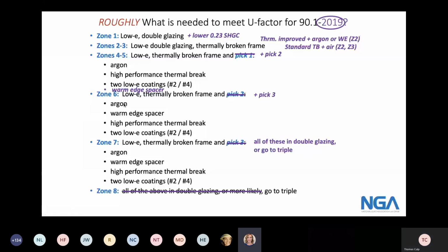Okay. Another related question. Why is there such a sharp reduction in U factor for commercial entrance doors from 0.77 to 0.63 in ASHRAE 90.1? Yeah, that's a good point. So we went through and just kind of surveyed some of the manufacturers, we meaning the ASHRAE envelope subcommittee, reviewed some of the thermally broken products out there for the commercial entry doors, and found that the 0.63 number was achievable and available and cost effective. Is the simple answer. So it is kind of like taking that next step.